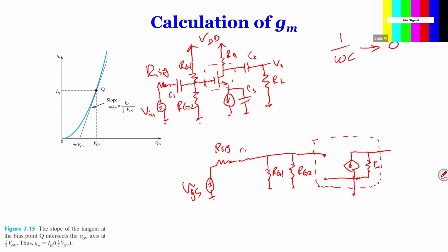What is connected to the source? That current source here is a DC source. It's got ID, some sort of DC current. For DC current, where you're doing superposition, you just know to treat it as an open circuit. So that one is an open circuit. I use blue, but it doesn't change the color. Okay, so that is the open circuit.